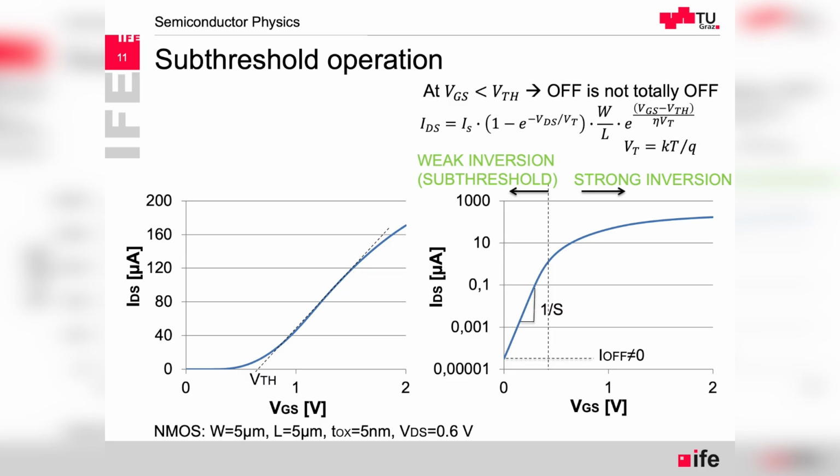On top of the static power consumption, of course, we have even more significant dynamic power consumption related to the switching action of the system. You probably know it from your own experience that when we want a processor in the computer going at a certain frequency and we want to increase it, we have to have better cooling because the power dissipation is so high that everything heats up much more.